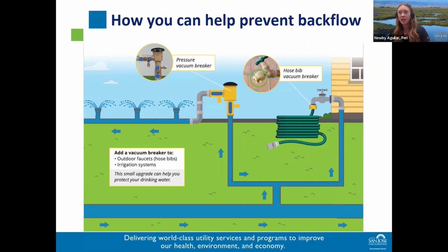In contrast, our containment operations, those you might see outside in the real world as you drive by, are what we call really large backflow prevention assemblies. They're large devices typically installed right at the meter. They are often found along the sidewalk or the property line. They're commonly visible in systems that operate containment-based cross-connection control programs. And they function as a way for us, as a public water distribution system, to prevent any potential backflow from that particular private property.